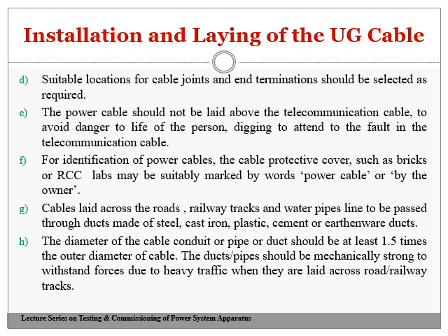Suitable locations for the cable joints and the end termination should be selected as required. The power cable should not be laid above the telecommunication cable, to avoid danger to the life of a person digging to attend to a fault in the telecommunication cable.